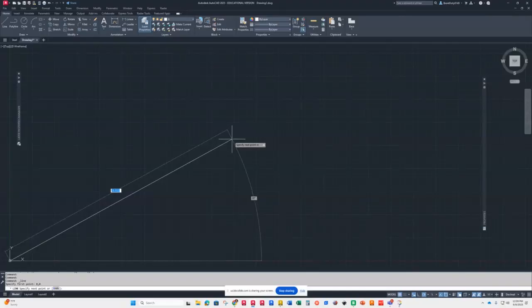So I can just draw a line. Pick a point or set a point and then hit enter or pick, and if you type in the information for the point and hit enter, it'll start at that point, or you pick and it'll start at that point. Well, then I can type in a distance that I want it to go. Let's say I wanted it to be 15. And then if I have a specific angle, I can hit tab. And then it will go over to the angle spot. So let's say I wanted it at 32. There's a 15 at 32 degrees.